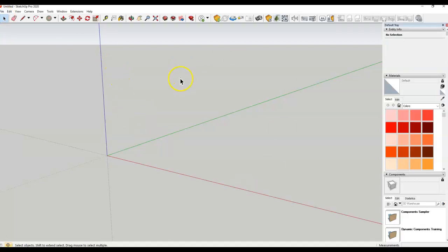The rest of the stuff we see here is not actually any modeled components. By default, just by what SketchUp has, this gray field here, that's the ground. This light bluish gray gradient here, that's the sky. Therefore, that's the horizon line, because SketchUp natively works in perspective. And so you have a horizon line. You'll see that as we begin modeling. And then the blue line, the green line, and the red line, which I will go over more in depth in class, those are basically just your orientations. They help you move. This is your 0, 0 point, as it's called. Again, we see it on the screen, but when you do any output, none of that stuff will be there.